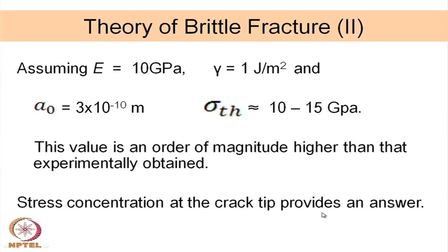So, before we do any experiment measuring the stress required for fracture, we assume that there are already cracks available, and those cracks are actually getting propagated, and that is how the fracture is taking place. So, it is the stress concentration at the crack tip which is of concern, and that is our point of discussion in the next few slides.